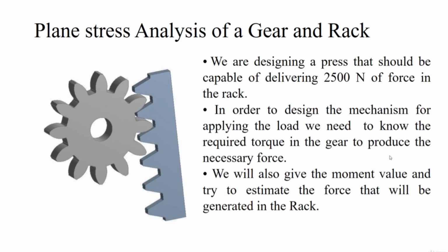Completing 3D successfully, now we are going to come to 2D problems. So what happens in the real world? Everything is 3D. There is no such thing as 2D bodies. So what happens is some problems can be simplified and then simulated in the 2D space rather than the 3D space. For example, there are problems like a pressure vessel where the vessel is symmetric around an axis, and the loading is also symmetric around an axis. That can be considered as an axisymmetric problem.